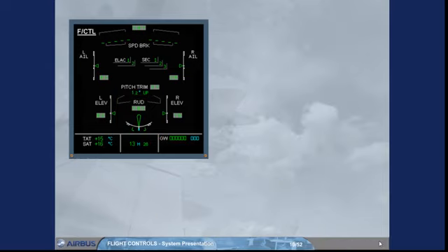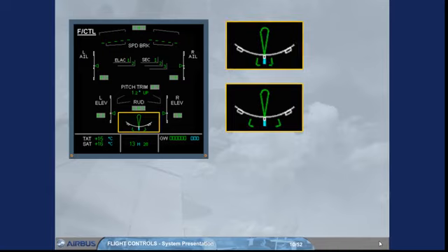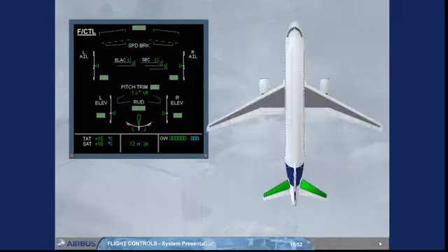Note that the rudder and the pedal deflections are limited as a function of speed via a rudder travel limiter. The travel limiter is indicated by two green brackets, which move according to the speed to a minimum deflection, high speed, or to a maximum deflection, low speed. The pitch trim position is indicated by trimmable horizontal stabilizer deflection in degrees up or down.